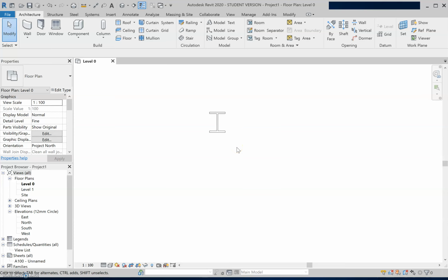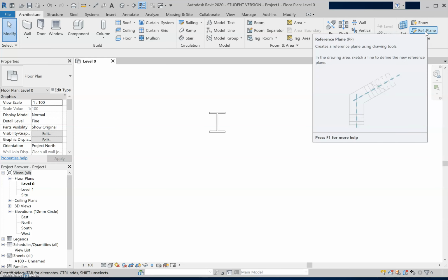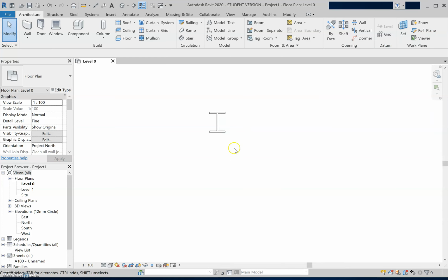So the other thing we wanted is a base plate. When you bring a base plate in, you're thinking about datums and where things are going. There's no reference lines on here. You could create them. So you could create reference planes and then decide where things are going. Depends how you want to do it. So we know that the reference plane is the 200 by 200 for the base plate, so we could start putting some things in here.